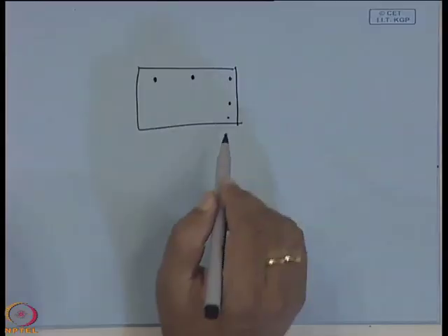When you talk about the thin film, basically it is a crystalline phase, it is a single crystalline film. If the lattice constant of the material matches well with the lattice constant of the substrate, then you can say that it is an epitaxial film.